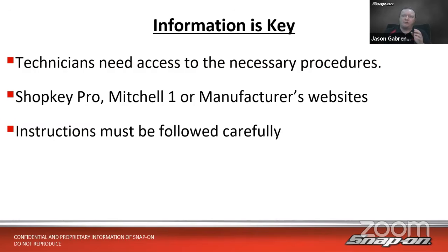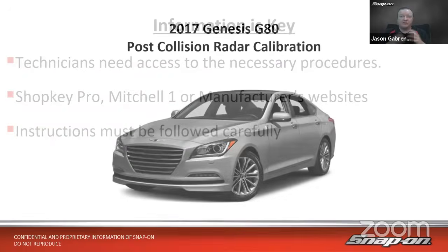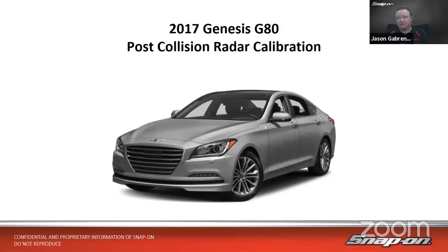You want to make sure you follow those instructions very carefully to the T. Do not skip any of those directions. If it tells you to cycle the key, cycle the key. If it tells you to take the key out, do that. Because if you miss a step, the calibration may fail. And worst case, you probably just have to do it again. But we want to make sure we're following the steps 100% carefully, because these are safety systems. We want to make sure we're being safe.